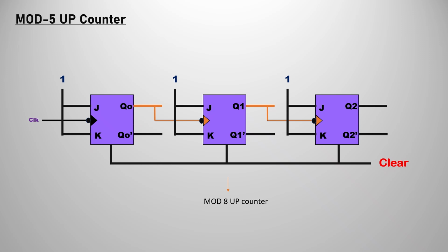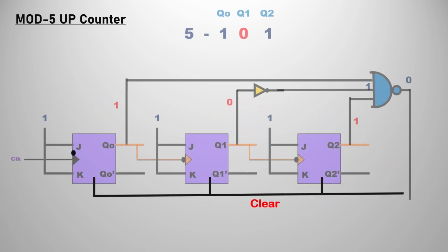Remember this thing, we are going to have the clear input signals also. That is a very important thing. Clear we have already discussed in the previous video. We have a separate video on clear and preset, so check out that video. I am giving that video in the description box. It will clear all the things. Whatever the outputs may be, if you pass clear as 0, the whole outputs instantaneously become 0. So that is the main use of clear.